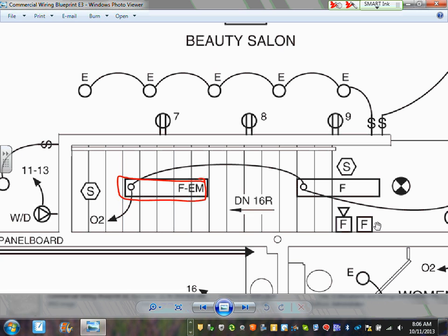These could be backed up by batteries, so if we lose the power intentionally or unintentionally, locally or globally. Intentionally, somebody's tampering with the panel there. Unintentionally, a short circuit happened. Locally, that thing is happening right at Dunwoody. Globally, a storm hit the transmission line and we lost power outside our jurisdiction. In all these cases, when you lose the power, the building code and electrical code require you to have an emergency light, because people panic, and when they panic, it affects life safety, people's life safety.